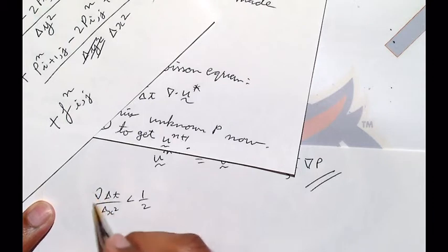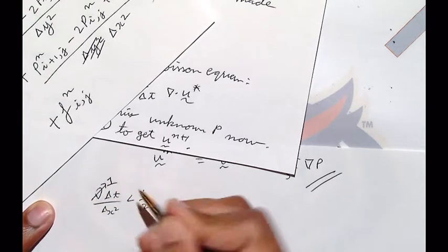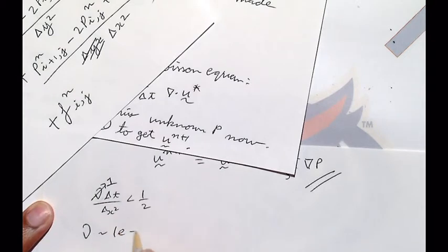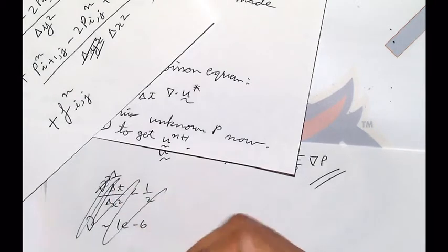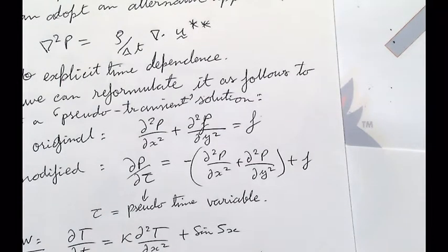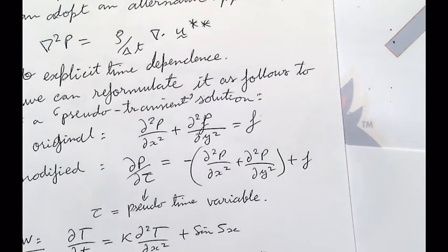Wait, no, now there's no nu. Okay, this is basically 1. So it's easier because nu is on the order of 1e minus 6. Yeah, so stability will not be an issue when you solve this pseudo time. You should just take delta tau to be smaller than the delta t, because you're doing intermediate steps. Okay. Any other questions?